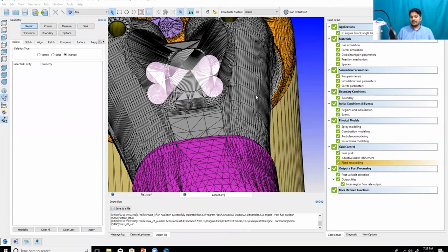It depends on the type of data that you have, but usually there has to be some type of data. It doesn't matter which CFD tool you're using, and it doesn't matter what type of simulation you're doing. You always need to first do a grid dependence test, make sure that you're getting an answer before we select a particular mesh or solution. So in this case, the 4mm base grid that I've selected is based upon several such simulations that I've run over the past 7 to 8 years. And the thing is, if you're using a different turbulence model, things will change completely.